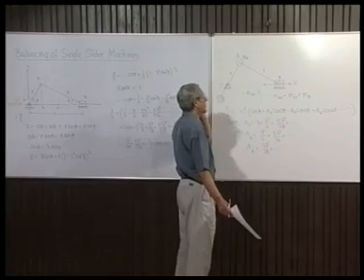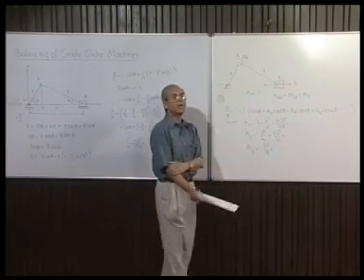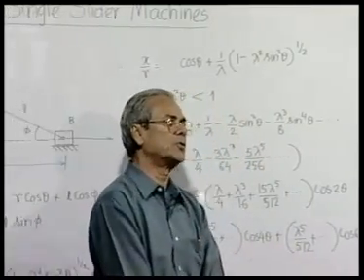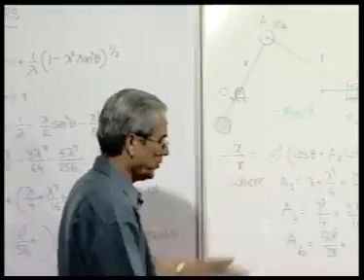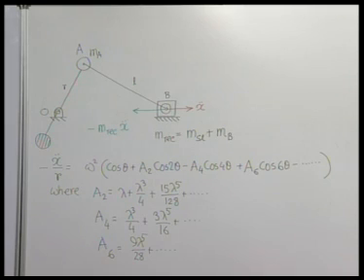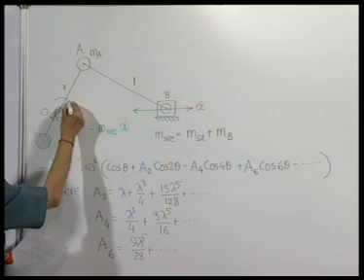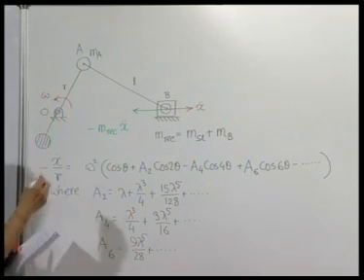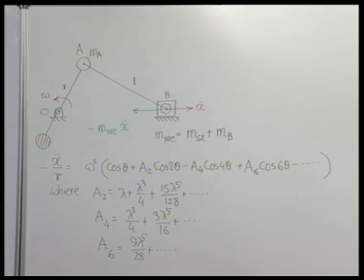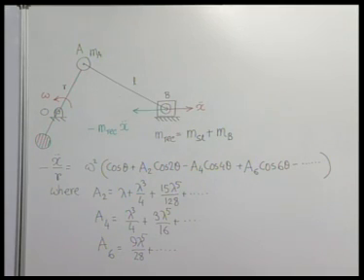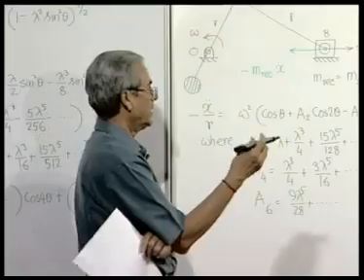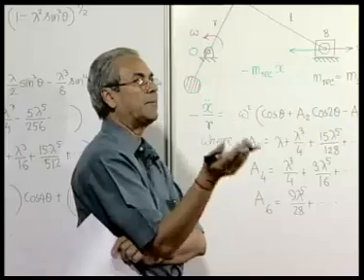Now, of course, if we have to work with this whole series, it is going to be a serious problem. What therefore we should consider is the practical situation. In most practical situations, the speed with which the cranks rotate, like say engines, normal engines, stamping machines or compressors, in such cases the lambda value is less than 1. So, we can ignore any term containing higher orders of lambda. That means, we can ignore from lambda cube onwards.